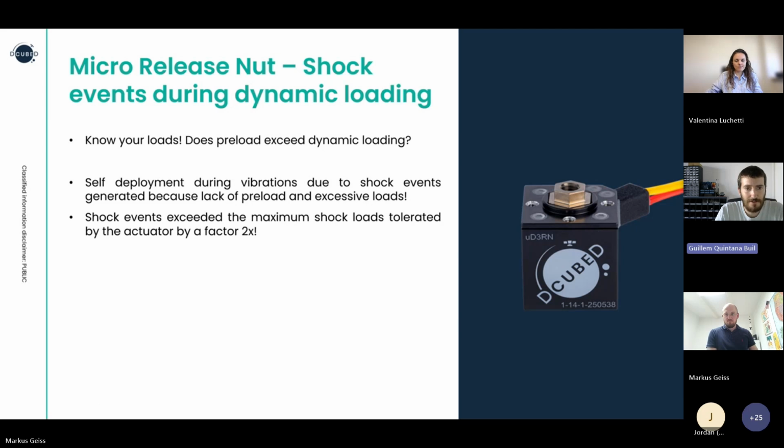The bigger the safety factor, the better, because if you apply a bigger preload than needed, it's all right, nothing wrong will happen. But the other way around is where the damage may start happening, especially, as mentioned before, if there are any fragile elements such as solar cells, optical elements, etc.